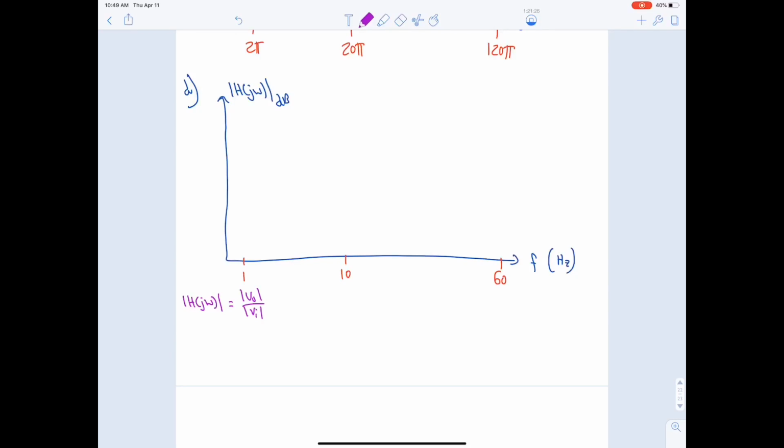So we'll do the same thing. At F equal to 1 hertz, the magnitude was 0.995. Okay, doing the 20 log 0.995, it has to be the absolute value also, will give us minus 0.04 dB.